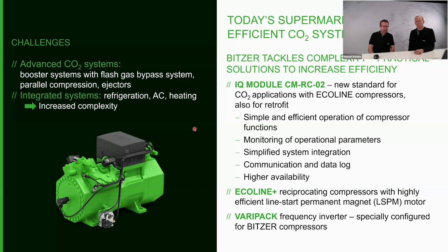With frequency inverter driven compressor selection, we had challenges with a high number of starts and stops, because if the compressor is too big, it starts and stops quite often if it cannot address the minimum load. Therefore, we have had some examples where we did retrofits. We replaced VARISTEP with the frequency inverter. In the wintertime, the compressor started, went to 25 hertz, and after 1 or 2 minutes, it stopped again, which ran fine for a couple of weeks or months.